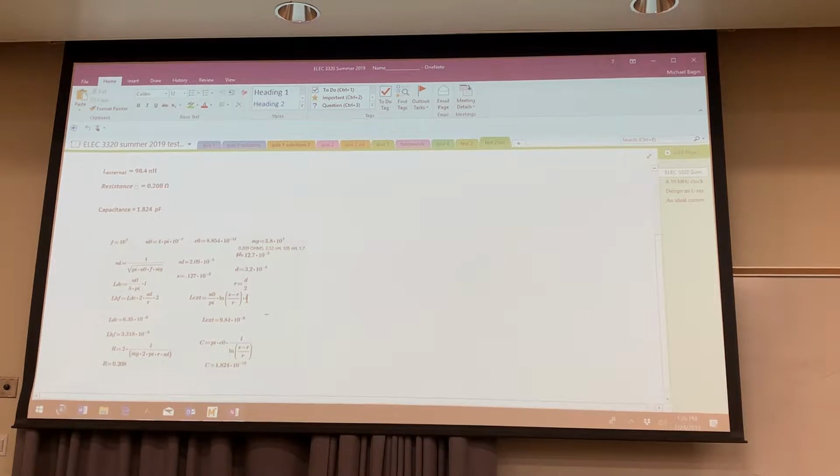After the external inductance, gotta get the resistance. Now remember, it's not one wire, it's 2. It's in differential mode, so it's up one, down the other. So the resistance is the length, which is 2 times the length of one wire, over 2 pi skin depth times the radius of the wire. Everybody understand? I'll post these. Okay. All right. Is everybody okay with that? Yeah. All right. And that's this one.